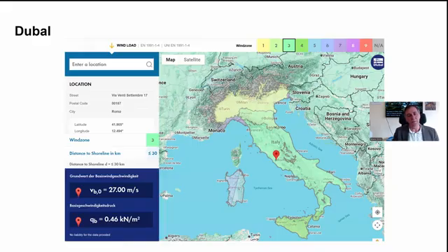And this is just an image from the national annex of the Euro norm. There is a global web page, where you can identify the actual basic wind velocity. Most of Italy is 27 meter per second, but there are other regions as well. As you see, the mountainous area is not marked. This is a special area.